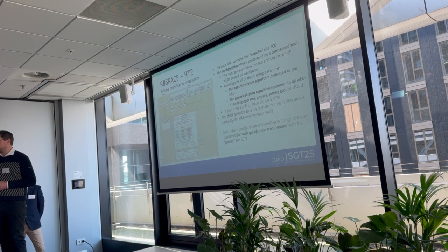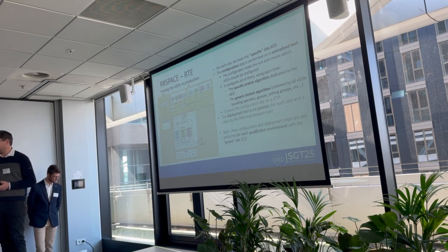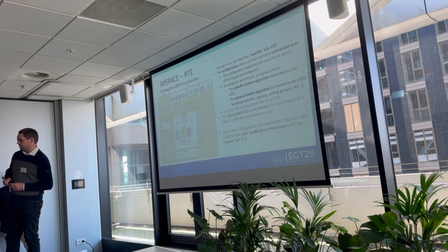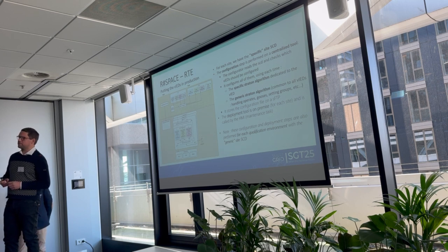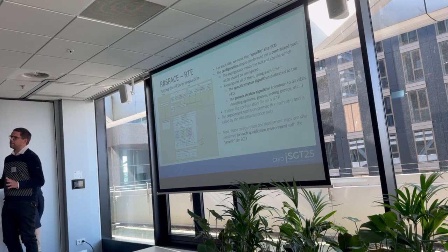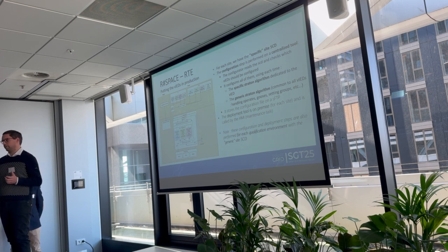And then once our virtual IEDs are all qualified, what do we do? We put them in production. Again, quite everything is automated. So for each site, we have a specific site SCD, as I said. I heard this morning, treat the SCD as your best friend. It's totally true for us. Everything is highly dependent on the quality of the SCD we have.